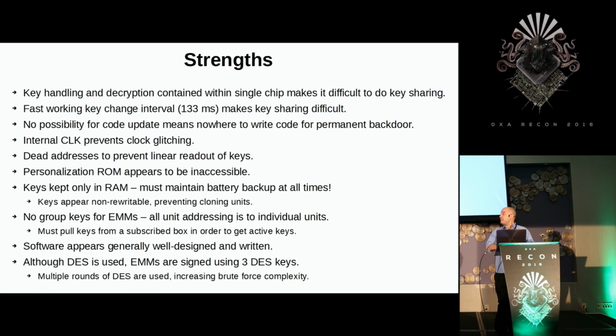The strengths, I was pretty impressed with the system overall, actually. The key handling and the decryption contained within one single chip makes it really difficult to do any kind of key sharing. The fast key change interval would also make key sharing very difficult. The fact that there's no possibility for code update means that there's nowhere that you can write a permanent backdoor.